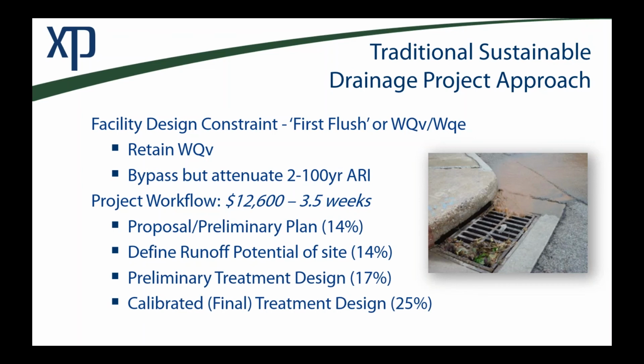And then what really comes to be slightly the majority of time, I will talk about that more in a second, but the bulk of the time on paper is still this calibrated treatment design system. So we've defined the runoff which will occur, we know where we want the facilities to be, but then we go back and forth and calibrate and iterate and find out what those need to look like to actually meet those requirements.